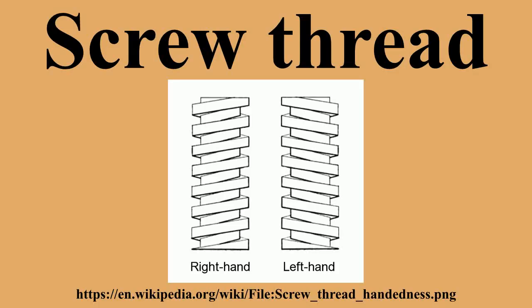The mechanical advantage of a screw thread depends on its lead, which is the linear distance the screw travels in one revolution. In most applications, the lead of a screw thread is chosen so that friction is sufficient to prevent linear motion being converted to rotary. That is, so the screw does not slip even when linear force is applied, so long as no external rotational force is present. This characteristic is essential to the vast majority of its uses.